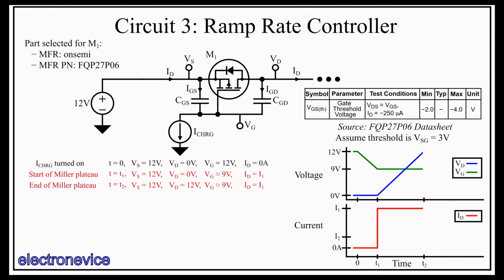The current I've drawn here is for a mostly capacitive load drawing a current of I1 during turn-on. Interestingly, under these conditions, it mostly doesn't matter what the load is. It could be a resistor, a capacitor, a combination, or a current source type load that turns on above a certain voltage. So how do we calculate the value of the drain voltage with respect to time in this plateau region? Well, we know that if VG drops by a tiny bit, the current ID goes to infinity, essentially. So in order for ID to be finite, VG must be constant.